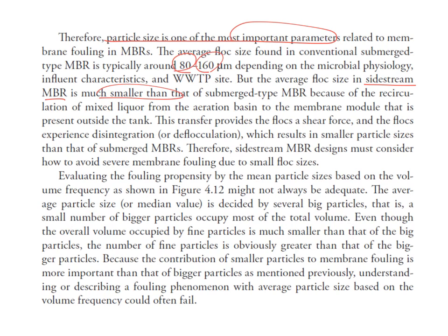So that's why side-stream MBR may have more severe membrane fouling compared with submerged MBR. This is another reason why submerged MBR is more practical compared with side-stream MBR.